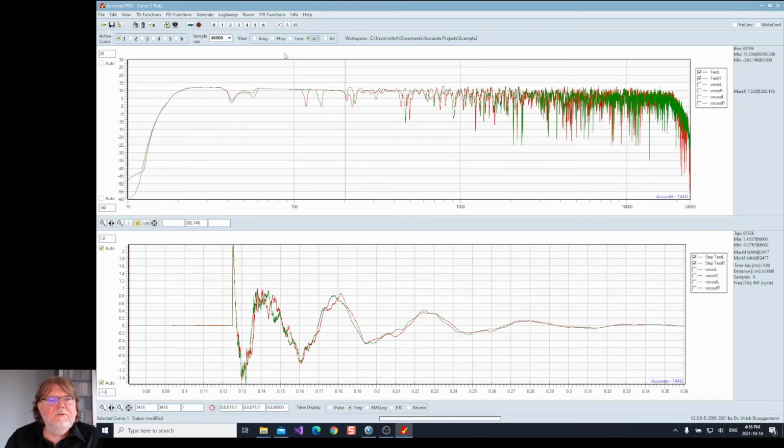This is the unfiltered, or projected simulated, frequency response that we're going to see. And if we applied some smoothing, like we would do in REW with the 1/6 octave smoothing, for example, the little dips are going to go away. We won't see that in the smooth response, along with, of course, the comb filtering. That will all be gone.